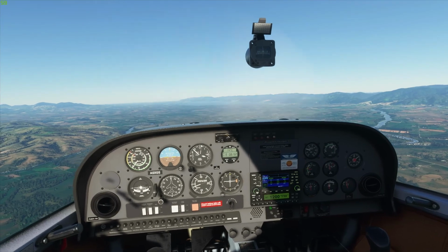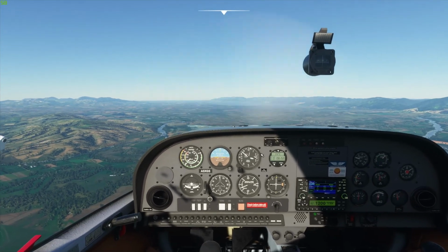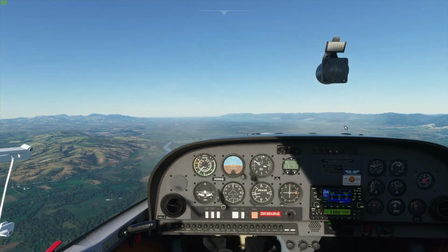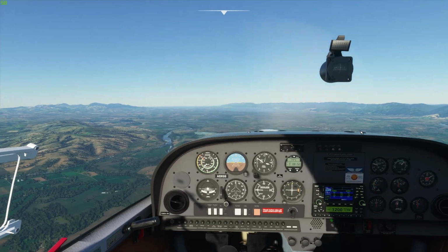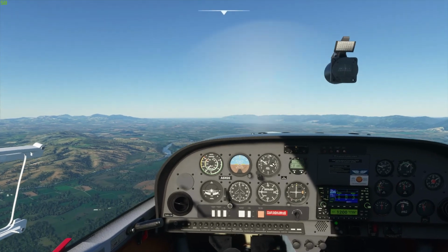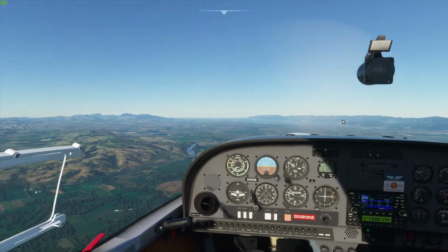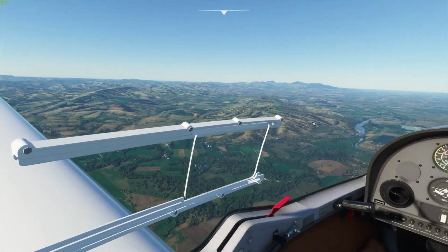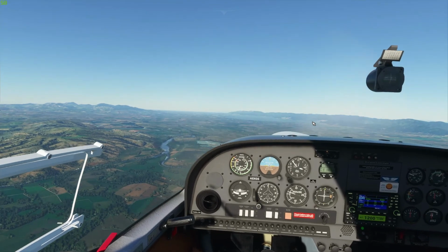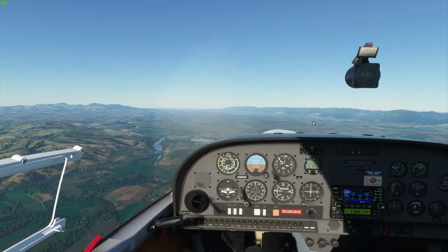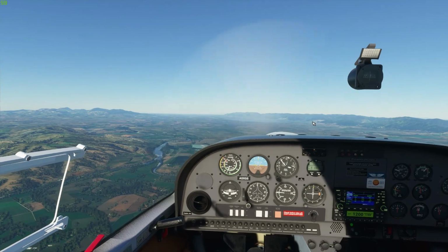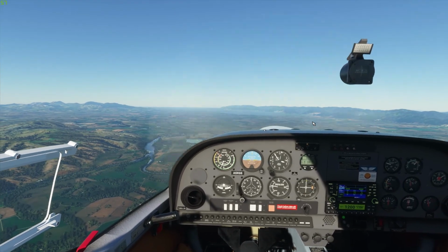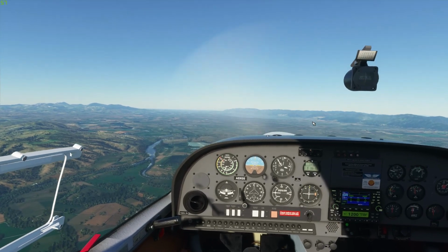It's 14 degrees outside, so it's around ISO conditions in 2992. Just retrim now for 20 inches of manifold pressure. And you could look around. Okay, so the first stall we do is what we call a clean stall. This is where we just close the throttle and just maintain altitude until the aircraft stalls with the flaps up. So this is a clean configuration stall.